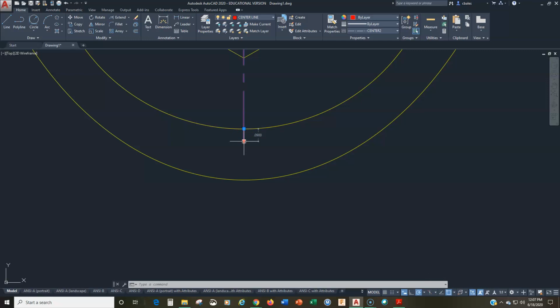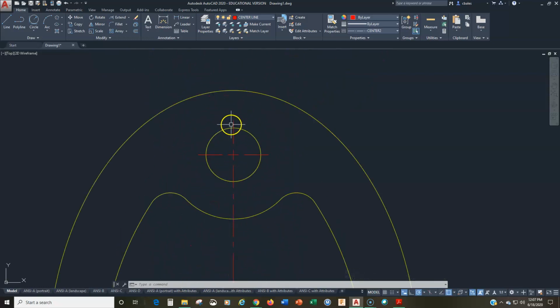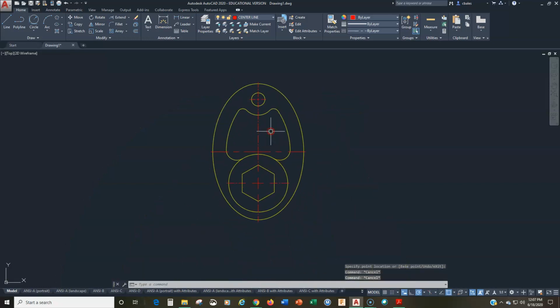It's a special grip, an extension grip or something like that. But notice the distance is already set to 0.09. So watch how easy this is. We grab the square grip and stretch it out to here, and it keeps that distance. All right. So isn't that nice? So we click on this, we grab that, and we stretch it out to right there. All right. Now we are done. No tricks. We are done with that. All right, so that's good.